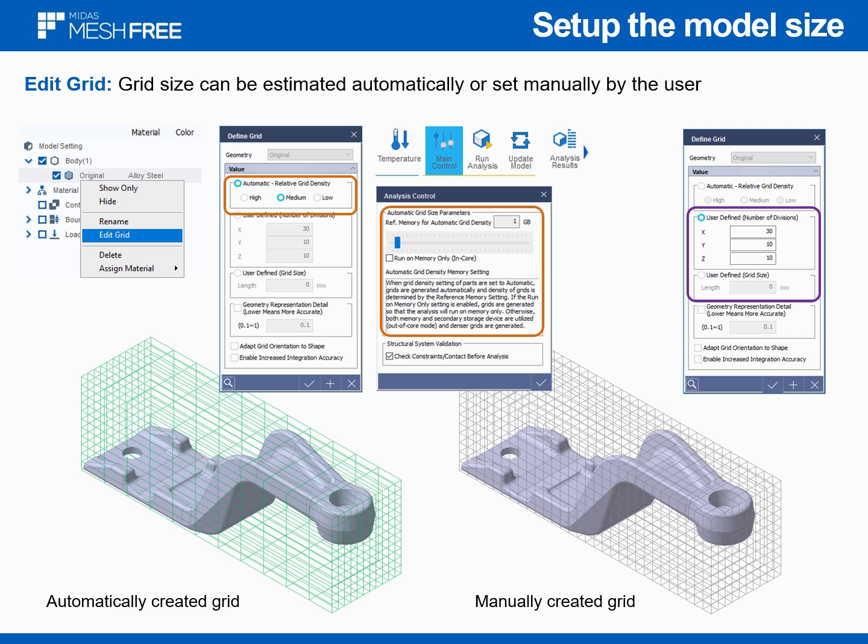So starting from manual, which is the easiest, please look at the right picture. When we click user-defined option, we can set up number of the blocks along X, Y, and Z axis. And because of that, our model will generate an appropriate number of equations since we are using adaptive method. Okay, so we have control only over the blocks, but these blocks are a reference measure of how big the model will be. So we can do this manually and we can do this automatically.